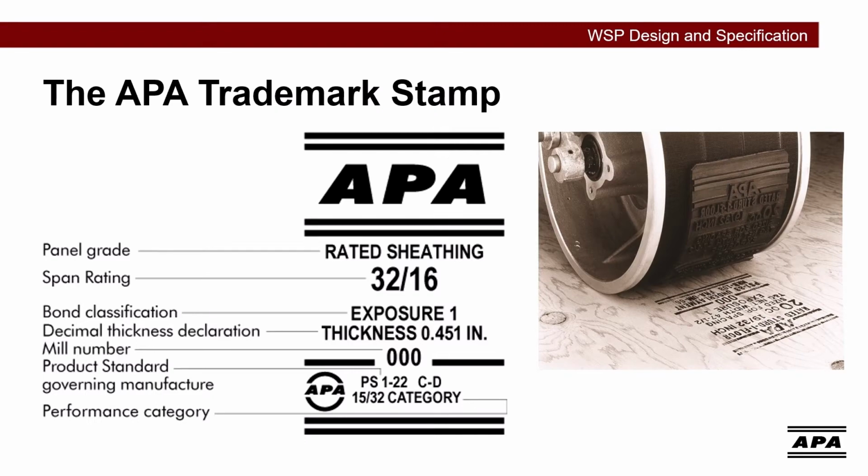To learn more about a wood structural panel, you'll want to go to the APA trademark stamp. This stamp is your key to understanding the panel's intended use and compliance with industry standards. So let's break down what you'll typically find on an APA stamp. First, you'll see the APA logo. This confirms that the panel has been manufactured under APA's quality assurance program. The second is the panel grade, which indicates the panel's intended use, such as rated sheathing, sturdy floor, single floor, or underlayment.